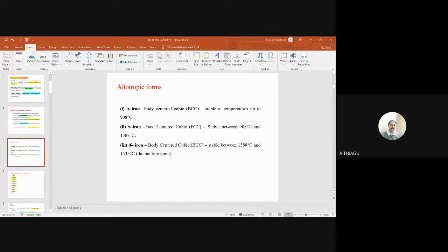It is a transformation from austenite to the formation of ferrite and cementite. So how it looks, it's like a thin layer of ferrite and cementite. I will show the picture. So the properties it has are relatively strong, hard and ductile. So these are the very essential properties for pearlite material. A very strong, hard and ductile structure.